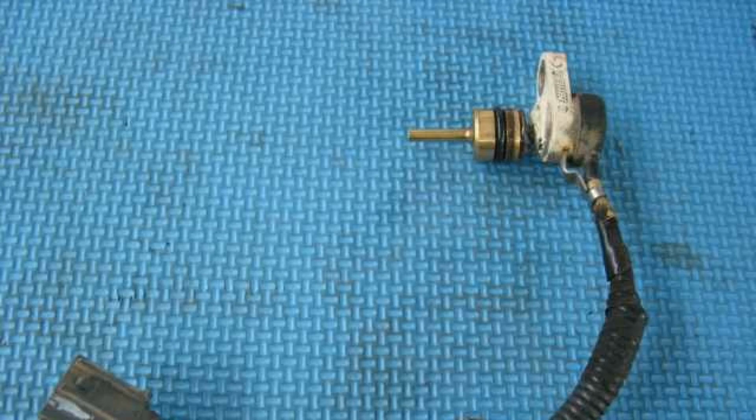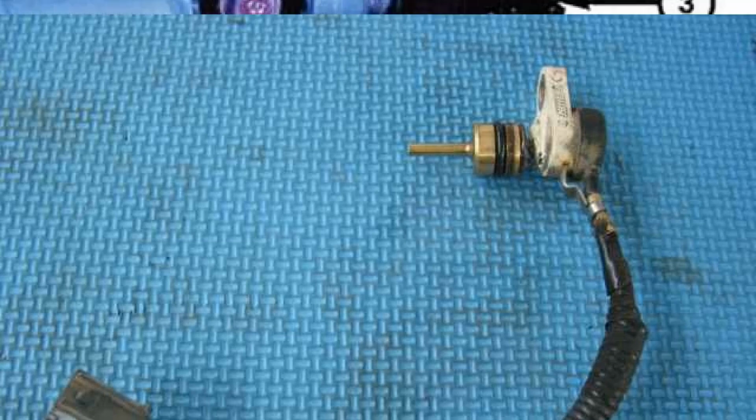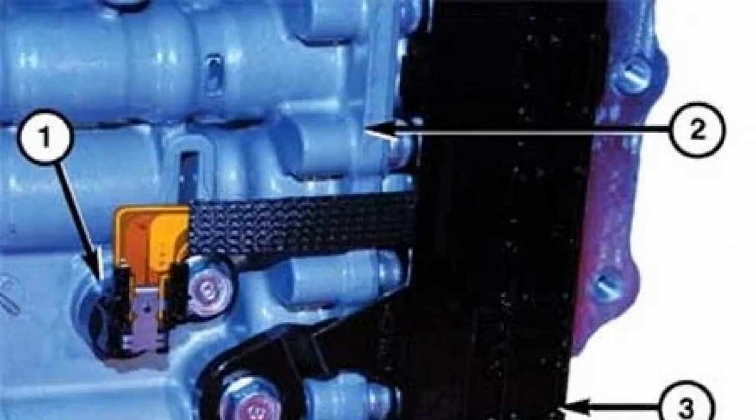Symptoms can include the check engine lamp on the instrument panel illuminating. The code will be stored in the ECM memory as a fault. The car starts in second or third gear, emergency mode. Unable to change gear. The transmission shifts hard or slips. Transmission overheating. Converter lock-up clutch engagement and disengagement problems.